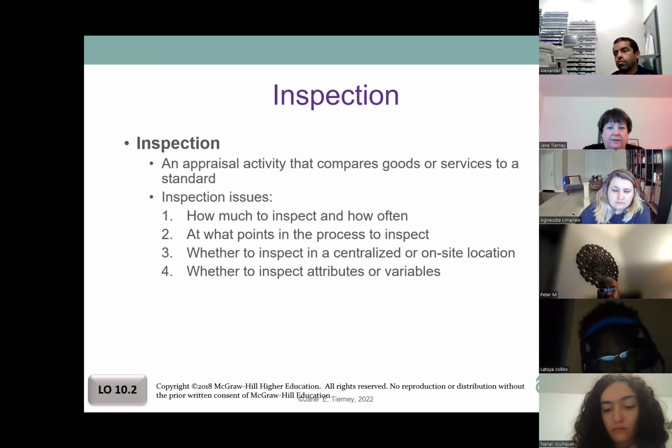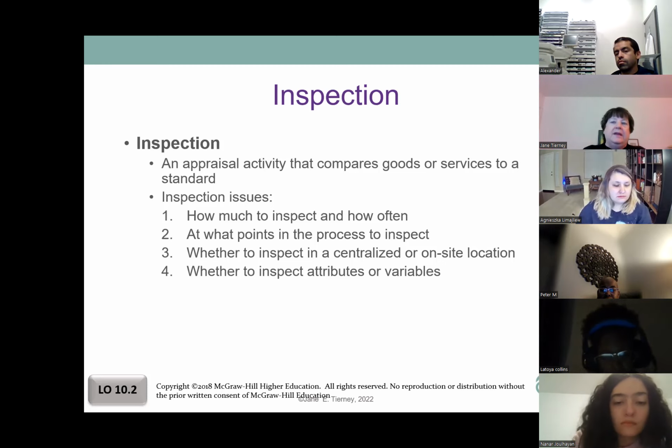So like if we had a drain where we were going to put a water heater, we want it nice and smooth, but we don't want it perfectly flat, because if there is drip drainage from that water heater, we want it to drain toward the drain.